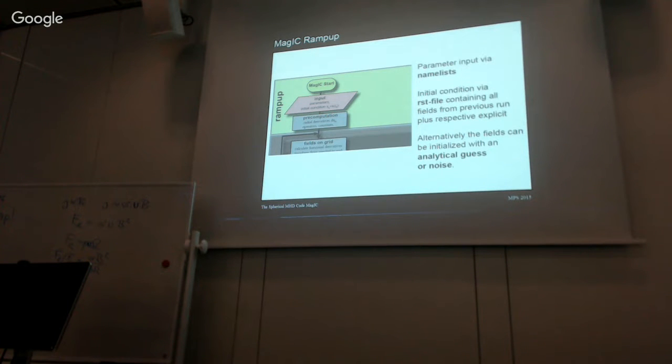So you integrate in time, but you start with a solution which is not truly a solution to your equations for the given parameters. So the numerics then takes a long time to adapt, to end up with something which is a sensible physical solution for the given parameters and resolution. So the closer you are, the shorter this transient is. So you save a lot of time, and it's particularly important if you have high resolution problems where your transient can take you a month to get over on the big computer, right? And it's money to save, basically.